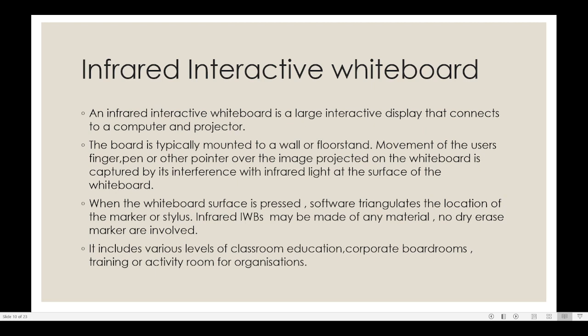So, infrared interactive whiteboard. An infrared interactive whiteboard is a large interactive display that connects the computer and the projector. The board is typically mounted to a wall or a floor stand. Movement of the user's finger, pen or other pointer over the image projected on the whiteboard is captured by the interference with the infrared light at the surface of the whiteboard. When the whiteboard surface is pressed, software triangulates the location of the marker or stylus. Infrared interactive whiteboard may be made of any material, no dry erase markers are involved.